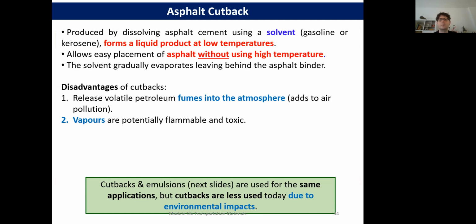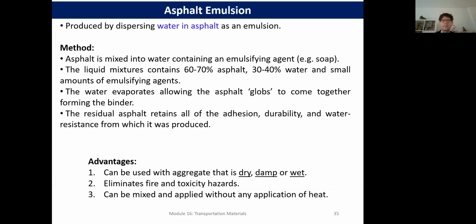When you talk about flammability, if you think back to some of the previous conversations I've had about high temperatures, whenever you have a gas mixing with oxygen and you have the right amount of heat, that can produce a fire. So you have to be careful. Cutbacks and emulsions, which I'll cover shortly, are used for the same applications, but because of the environmental impact, you'll see cutbacks used a lot less.